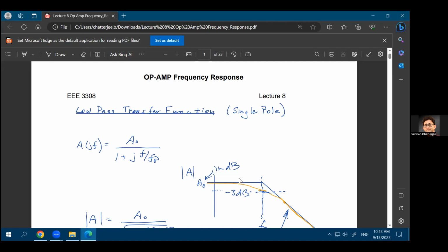So you have this circuit that, okay, you are providing some voltage. Again, let's assume that you have a voltage source over here. You have a resistance, which is this resistance RO, and you have a capacitance of C0. What is this circuit? Does this circuit do some kind of filtering? And many of you already know about this, that, okay, yes, this circuit works as a low pass filter. Why does it work as a low pass filter?